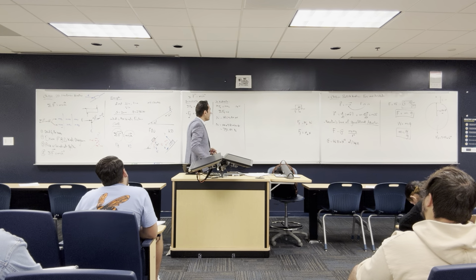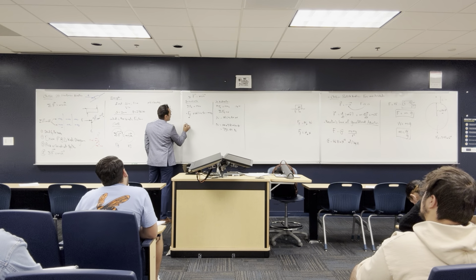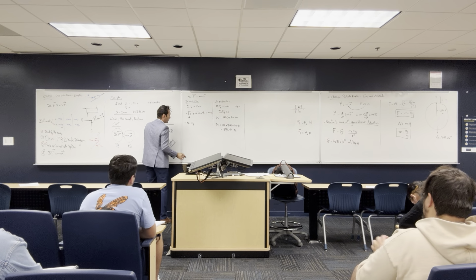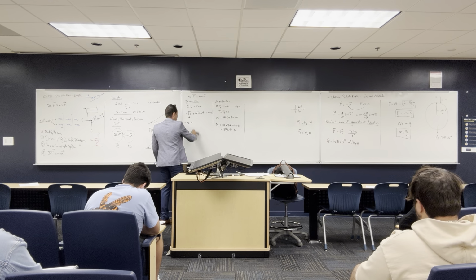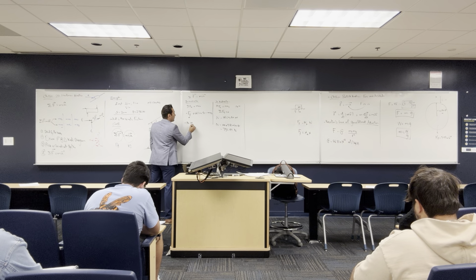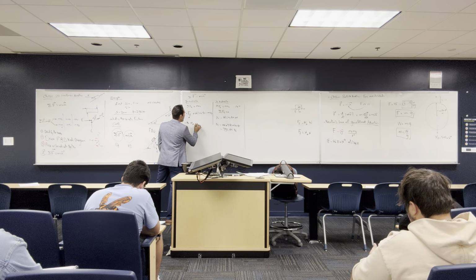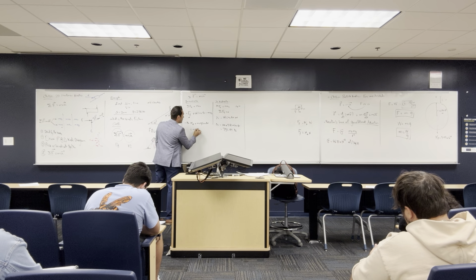All right, so here, basically I can say that this is equal to N multiplied by mu friction, or mu dynamic, and that's actually what I'm asking for in the problem. Mu dynamic. Plus W, which is going to be M multiplied by g sine 40, and this all should be equal to M multiplied by a_x.